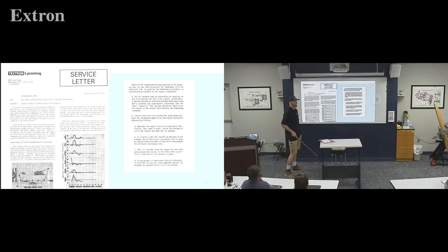Now that said, some of these were like, switch your oil out after 5 hours if we suspect damage. Well, you might have to tell the people what's going on then. The oil sample must be clean. Be sure the area around the drain is perfectly clean before the sample is taken, so that means before you pull the plug, wipe the drain off. Filter tube too.